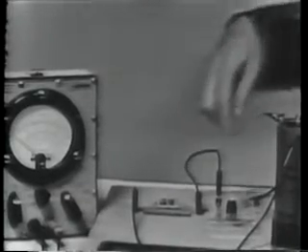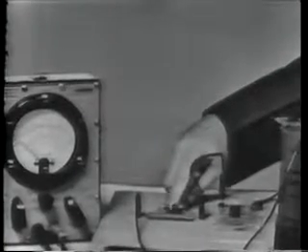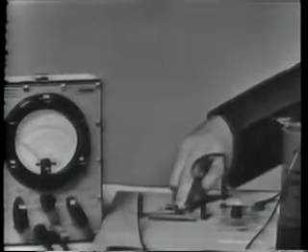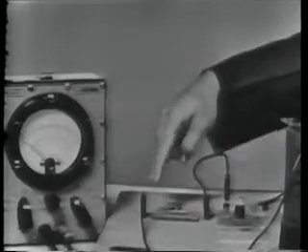The rule is, when your voltmeter is across the open component in a series circuit, you'll read the battery or applied voltage. I'll show you an actual circuit identical to this one. There are 2 batteries which together supply the total voltage in the circuit. I also have a 5-ohm resistor. This resistor is open and connected in series with the lamp.